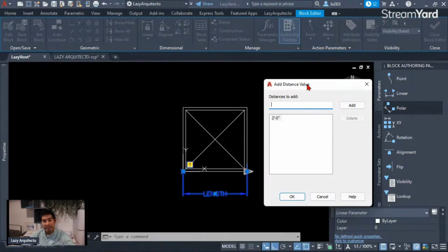How do we do that? By giving them only two or three options, using the standard diffuser or return sizes. We don't want to give them unlimited options, as they might pick, hey, a 4 feet 2 inches diffuser size, you know what I mean? You want to guide them, so they have three different options to pick, and everybody using this block would work more efficiently.